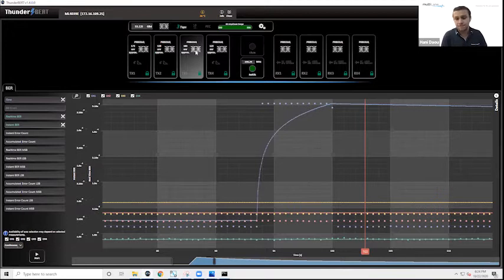Now, FEC is a tried and true technology that's been around for a long time, but this is the first time it becomes a mandatory encoding mechanism for data center interconnects, for optics that are meant to go not across cities, across oceans, but shorter reaches, still within a data center campus. To give our customers full visibility on FEC behavior, we have implemented real hardware-based Reed-Solomon IEEE compliant forward error correction in our flagship BERTs.